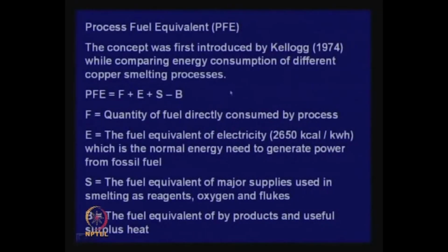Are you consuming any electricity? If you are consuming any electricity, then E, what is the fuel equivalent of the electricity? And for that there is a well known conversion, that is 2650 kilocalories per kilowatt hour, which is the normal energy need to generate power from fossil fuels. So, the energy input into the system in terms of solid or liquid fuel or electricity, you first calculate.